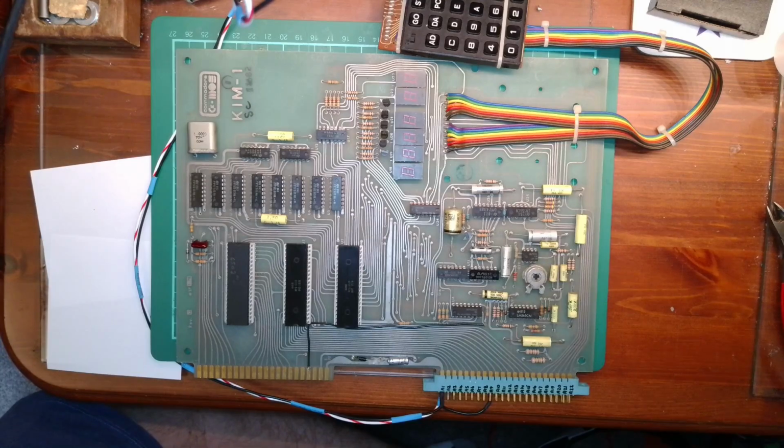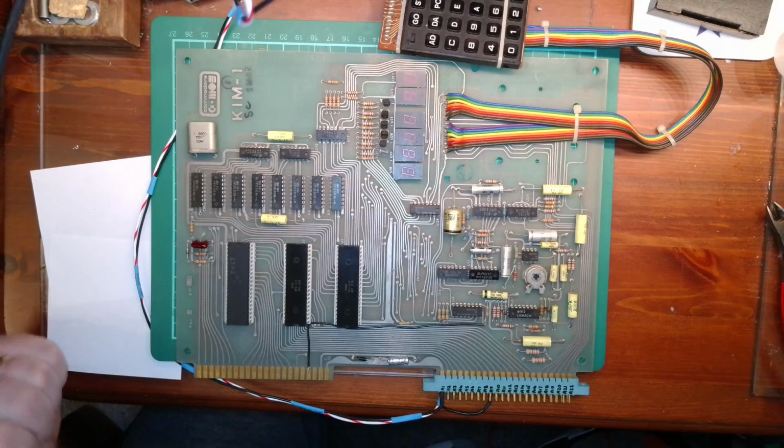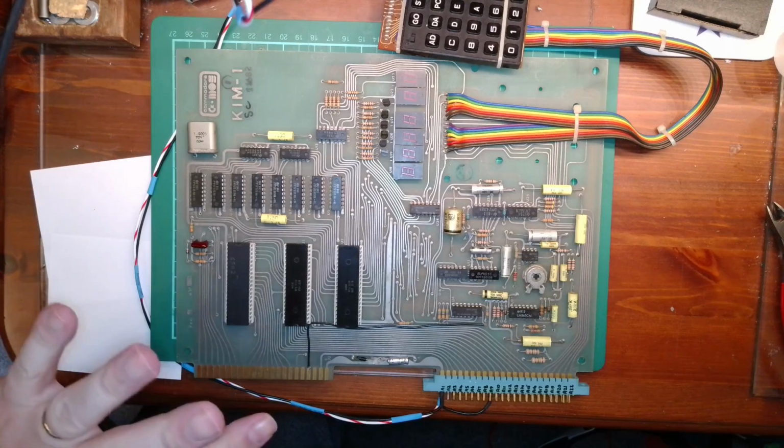That basically makes the bottom 8K addressable space repeat itself every 8K. When the 6502 starts up, it looks at the top 4 memory addresses to see where to start from. 2 of them are the interrupt vector, and the other 2 a bit lower down are the actual startup vector for when the reset is pressed.